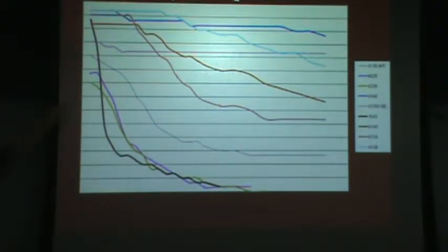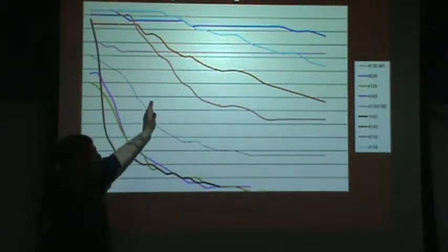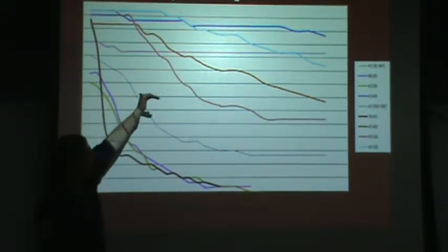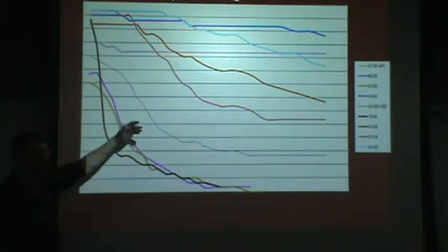These over here, say this green colored one, this is the 4320, so lower carbon. The rest of the alloying elements are similar to what's in the blue 4340, but you see that the as-quenched hardness on the very end is quite a bit softer. So we see the effect of carbon at J1, and then as we progress through the rest of the graph, we see how hardness is either fairly stable or not very stable, depending on alloy content.